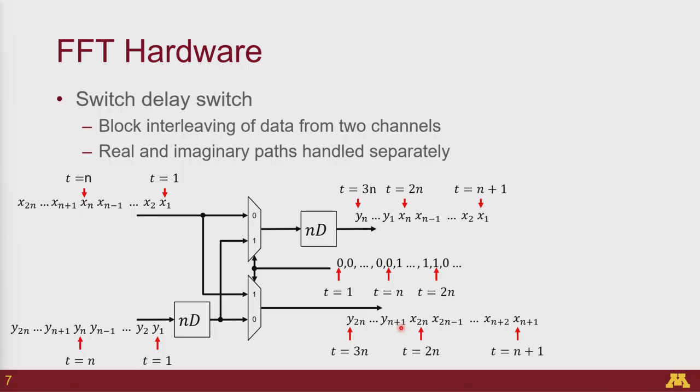So to break the critical path, they have to have a pipelining cut set. Yes, right. So even though there are registers present here, it does not break the critical path. So if you need to actually break the critical path, you need to insert your own manual pipelining cut sets.